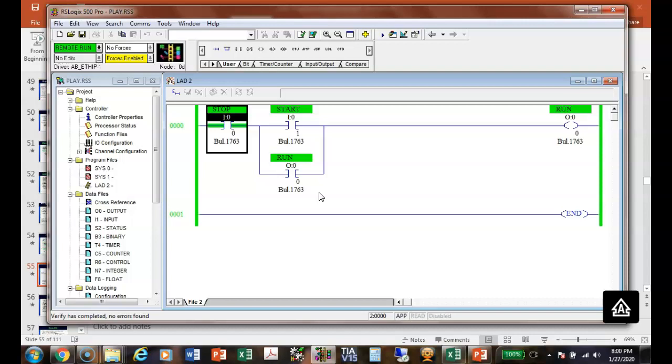In motor controls, you'd go crazy because you want to see it as a normally closed contact, but that's not a normally closed. That's an examine if it's true if it's closed. So is a stop button normally closed? Yes. And we're using examine if closed, or if true if it's closed instruction. This guy right here is a normally open push button, and it's what we call an examine if closed instruction. But I'm going to use a momentary contact, so I'm just going to come up and touch this thing, and it sealed itself in.